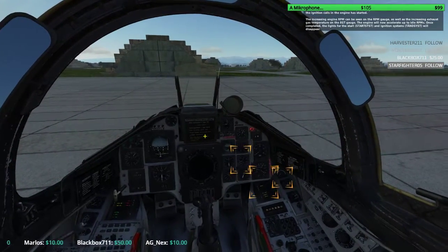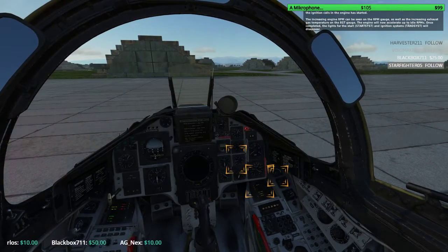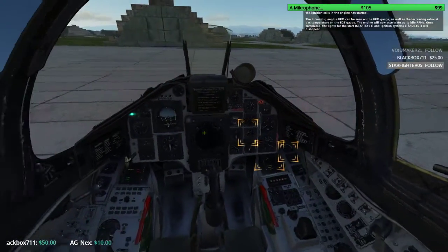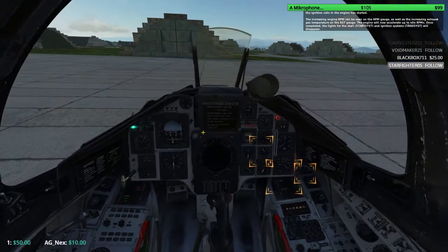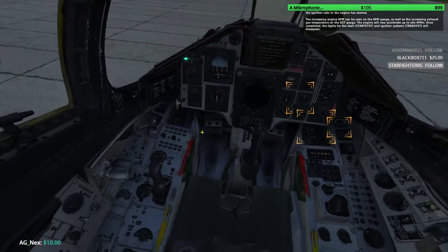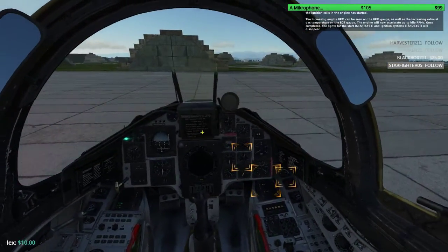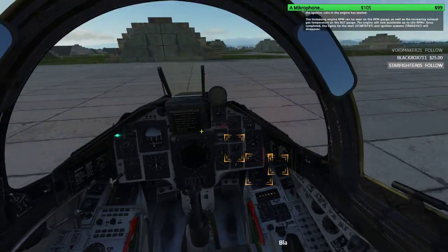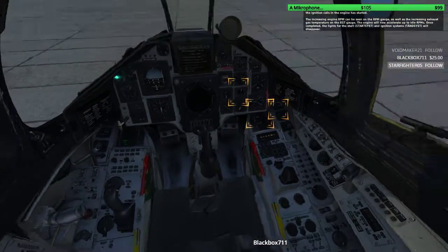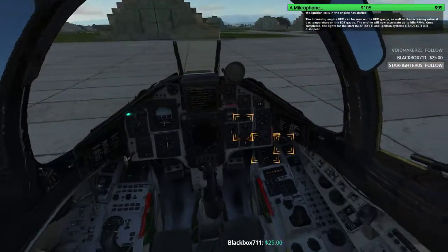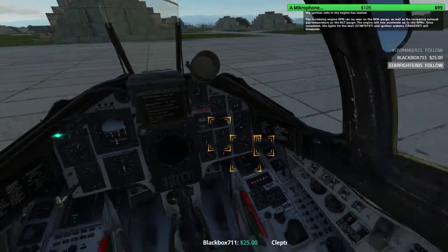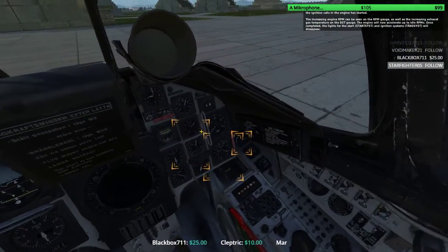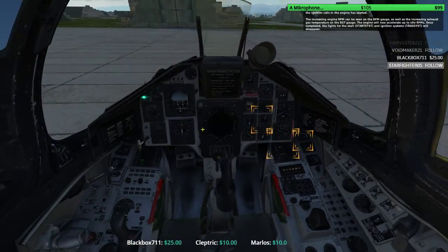The gas turbine starter will now start powering the gas generator of the engine, as seen by the increasing RPMs. The ignition system's light will appear and indicates that the ignition coils in the engine have started. The increasing engine RPM can be seen on the RPM gauge, as well as the increasing exhaust gas temperature on the EGT gauge. The engine will now accelerate up to idle RPMs. Once completed, the lights for the start and ignition systems will disappear.